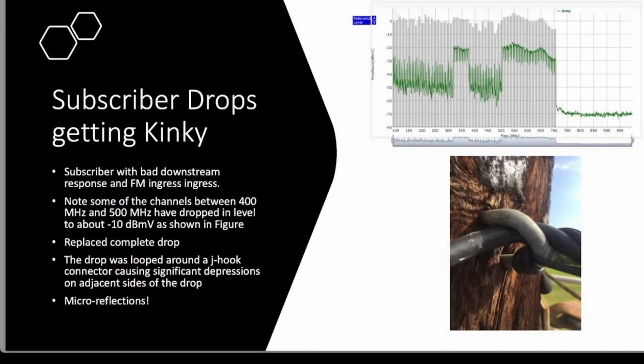Correct. So speaking of standing waves and filters, I want to go back to the slide here. Last episode we talked a lot about full band capture. If anyone's not familiar with full band capture, please go back and watch our last episode. Here we see a full band capture that has a little bit of a standing wave in it, and more severely, we see a lot of high frequency roll-off. So if those are DOCSIS channels, the modem may have a problem locking to those highest frequency DOCSIS channels. If they're video channels, the set-top box may have difficulty locking to them.